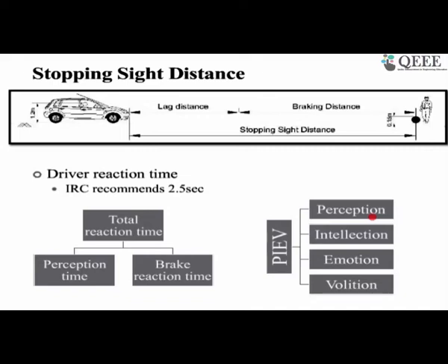And again, it could be a design fault as well. So one aspect is the traffic operation fault, another is the design fault. If there is a sharp curve at the intersection and you cannot see the main road, then of course that is a design fault. And for an alignment fault, if you want to consider a bypass, or whether the curve was quite sharp, then you may consider it an alignment fault to some extent. So it depends on that.